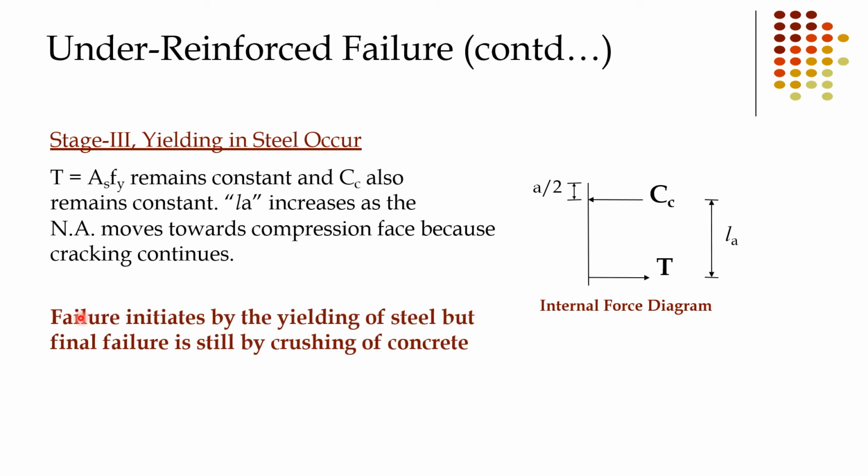Now the result: failure is initiated by the yielding of steel, but final failure is still by the crushing of concrete. That's the under reinforced failure philosophy. Failure initiated by yielding of steel, but the final failure is still by the crushing of the concrete, meaning first steel will yield, then concrete crushes.